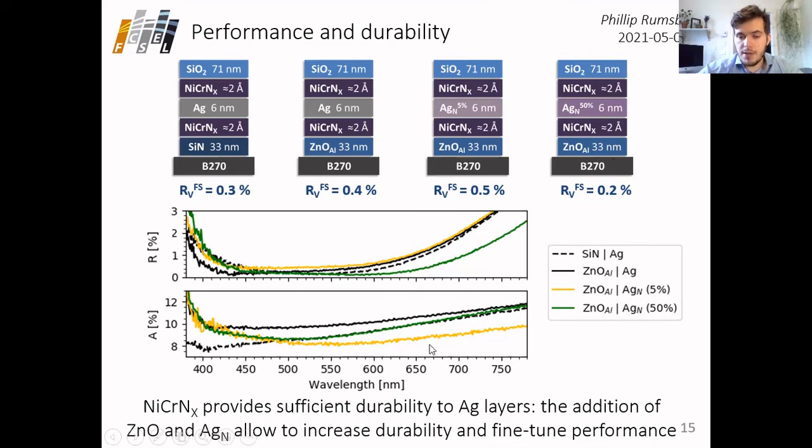We get a significantly lower absorption of about 1% lower. And this is quite interesting because it also comes with a slight decrease in the sheet resistance for this layer, which suggests that the increased coalescence and the increased grain size at once, being in between these two, is giving it better conductivity.